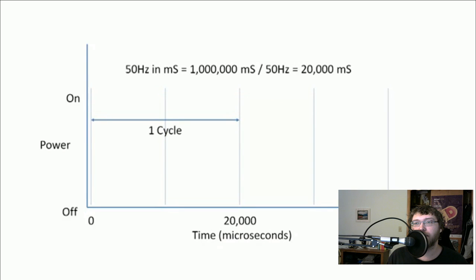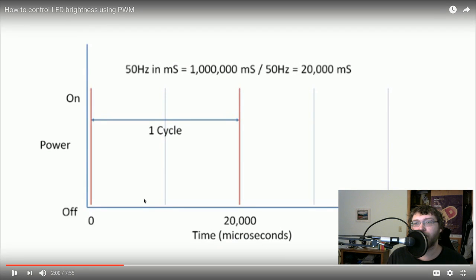The cycle itself is measured, usually, in Hertz, which gives us the cycles per second. So this is the thing that really clarifies it for me. We're targeting 50 Hertz in this example. And so if you do the math, you get this 20,000 here. And then you see, here's one cycle, and then the duty cycle over that, we break it up into units.